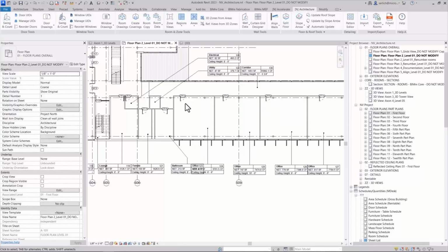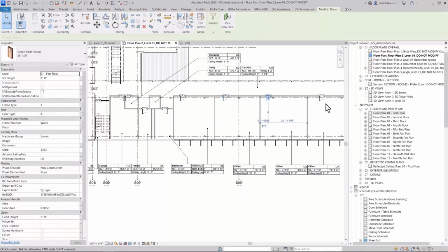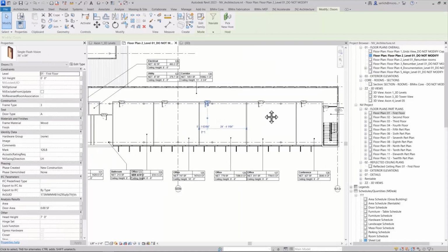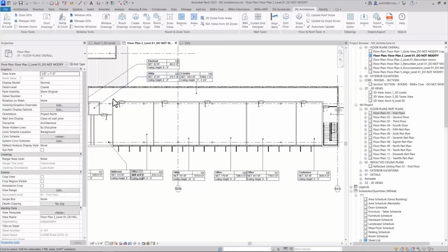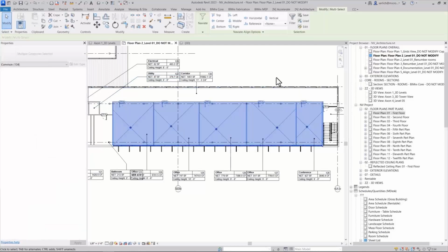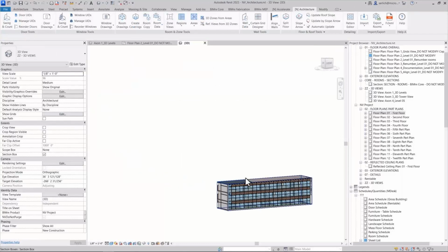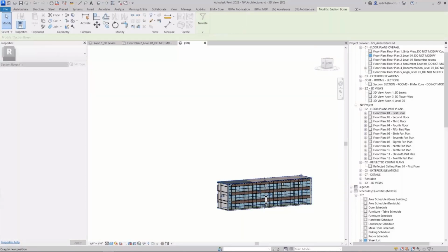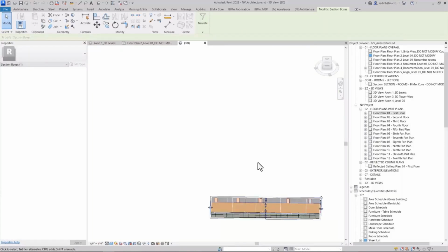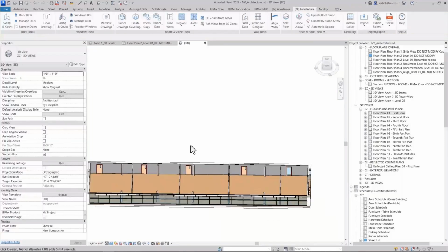Like I said, first we're going to start with that move to nearest feature. And we see here that I've maybe redesigned my walls, and now my doors are kind of different distances away from my walls. So I want to use my move to nearest to align them. The move to nearest feature does work only in a 3D view. So I'm going to select the doors, create a 3D view that showcases them so that I can then use the command and align them.